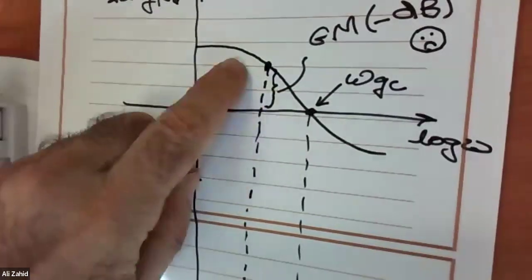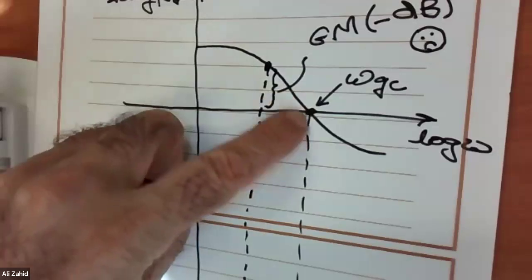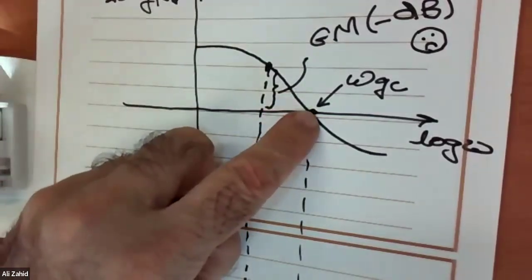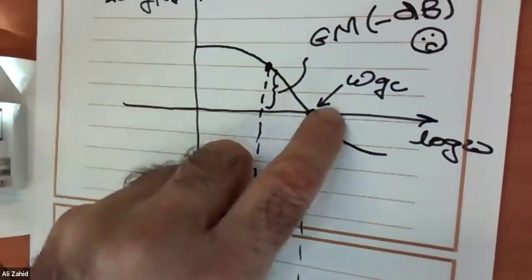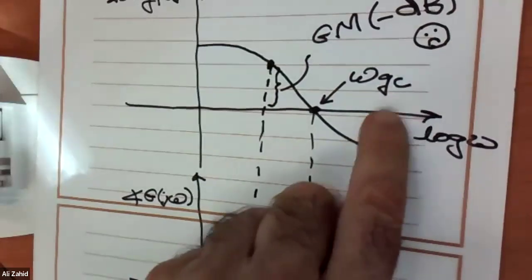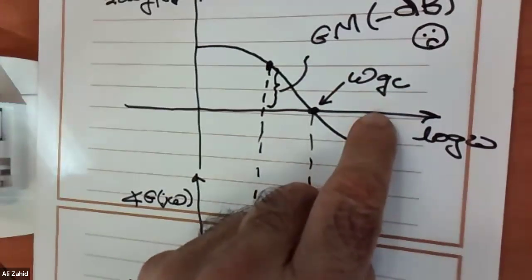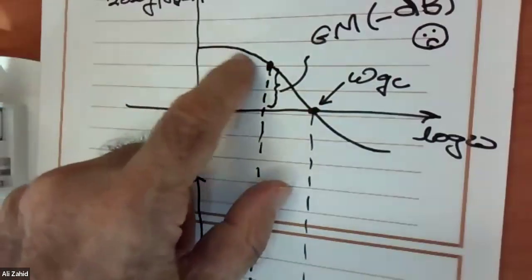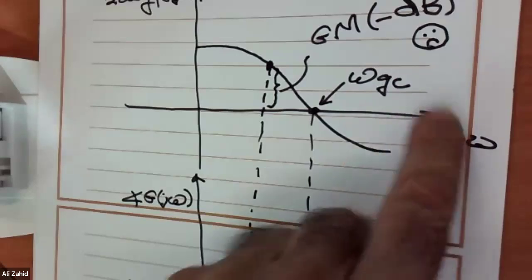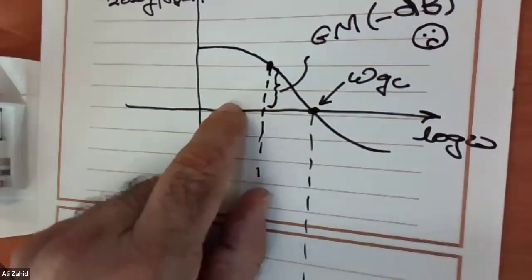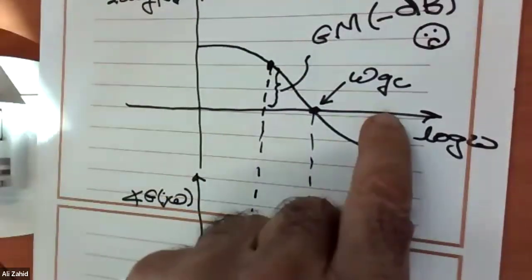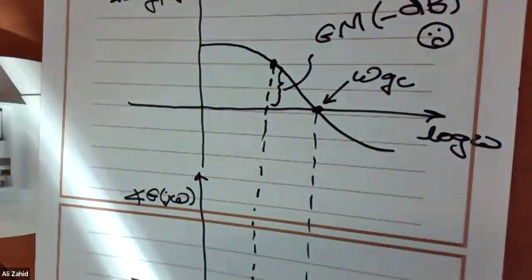Which means what? I need to reduce. See, the steeper this curve is, what does it mean? It means it will hit what? If you move this one to this side, which means what? This is a pole frequencies because the Bode plot is going down. So you are putting the pole on here. You should put the poles where? Here, so that this one drops sooner rather than what? Later. Yeah.